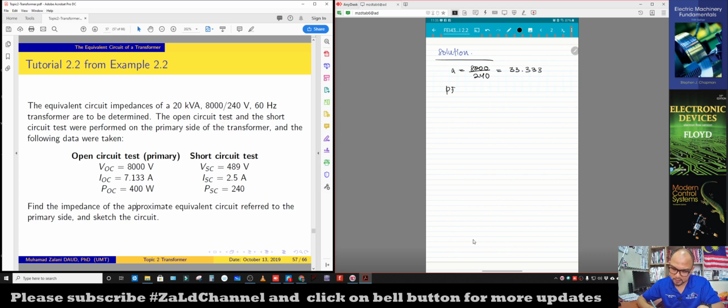So power factor can be determined by using PF equals cosine theta, from the equation. We know that cosine theta is the power of open circuit, POC, divided by voltage of open circuit times current of open circuit.